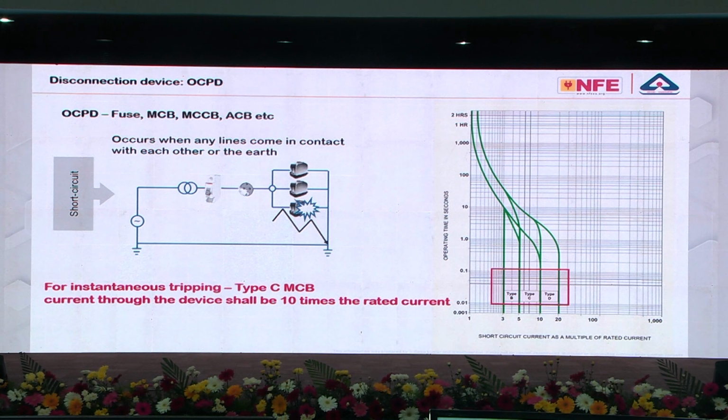Imagine you have an MCB, and you are not using an RCCB because you have some machines or a group of machines which is creating a leakage current. RCCBs of 30 milliampere will trip. RCCBs are not used everywhere. RCCBs are used as an additional protection in certain places. You cannot use RCCB from A to Z because it creates nuisance tripping, which is against electrical usage.